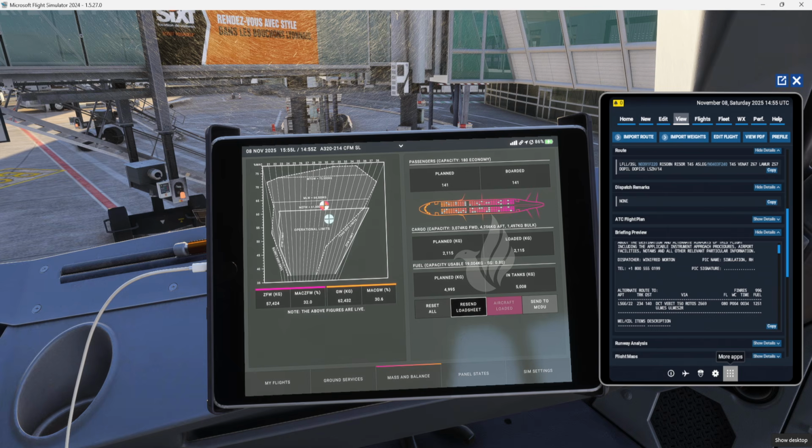So I'm going to stop at the zero fuel mass because this is the interesting part. Why do we calculate the zero fuel mass? We determine it to see if we have passed the structural limits of the aircraft, because the aircraft has a maximum zero fuel mass. We need to calculate our zero fuel mass in order to see if we have passed the structural limits.